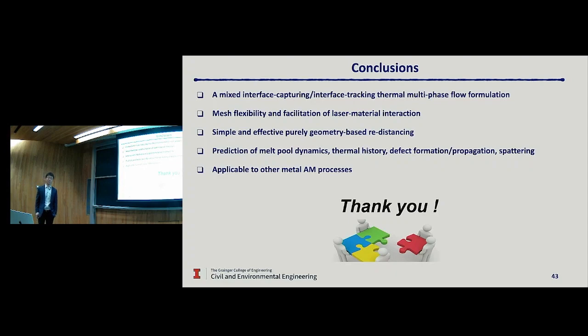Very nice presentation. And I apologize, maybe I didn't understand this correctly, but when you were talking about the speed of the scanning, it seemed like you talked about the force fluctuation stabilizing. My question was, the faster that you go, might there be less fusion? It seemed like it was asymptoting to something, but you could go so fast. So what does that mean relative to your result? Or is it that the force fluctuation is low, and it would be another graph that you'd have to look at to tell the quality of the material that's deposited, or that fusion of the material?